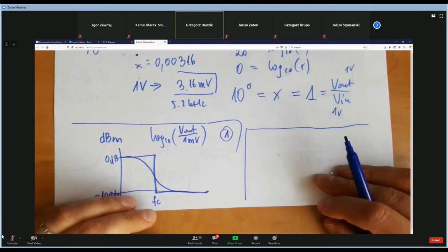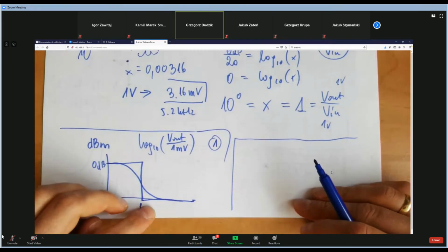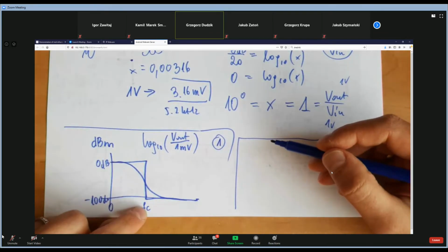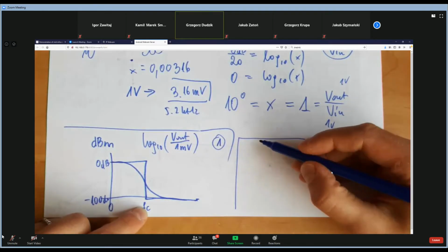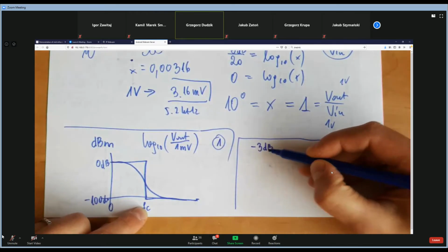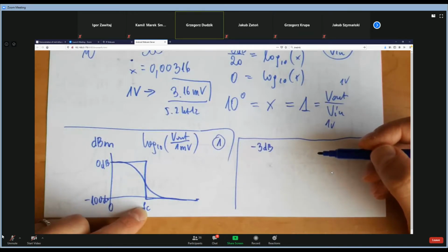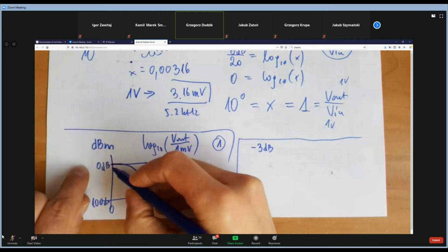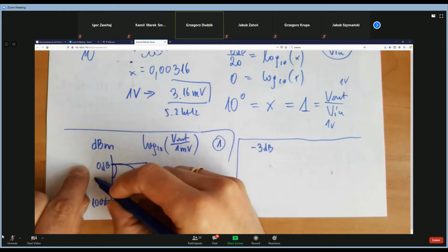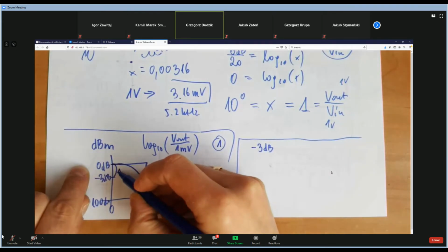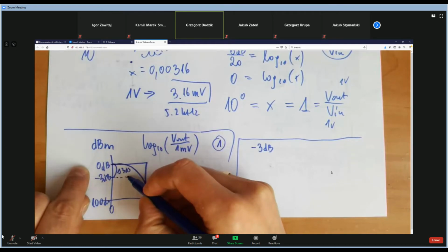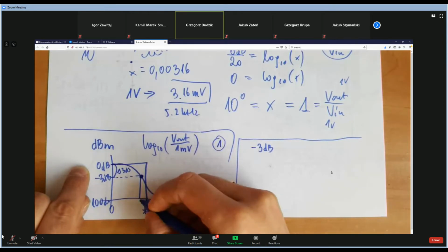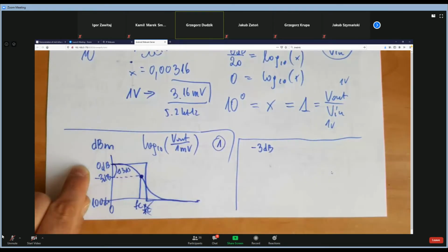And in electronics, people decided that the point where we get the cutoff frequency is the -3 decibels position. It means that if we have the maximum amplitude here, we have to drop it by minus 3 dBs. For this point, we read the frequency, and that will be the cutoff frequency for the filter.